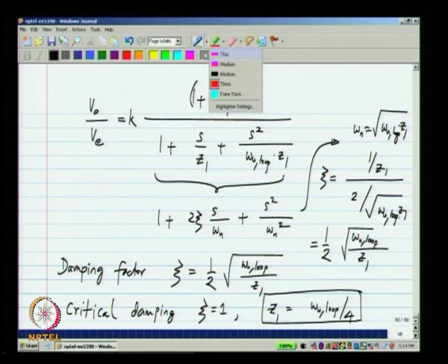Okay. Now, we also see that from this particular expression, if you move the 0 to lower and lower frequencies, the damping will become more and more. Okay. You will have higher and higher damping factors, and if the 0 approaches the unity loop gain frequency, if it is equal to the unity loop gain frequency, the damping factor is half, which is acceptable, but it will have a slight ringing. Okay. Anything lower than that, you will have a lot of ringing. Okay.